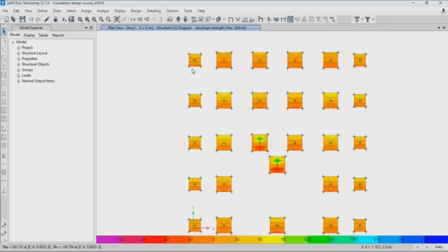Okay, so what it does is it designs the footing based on the pure physics of a flexing shear element. It is going to evaluate the exact stress at every single localized point in your mesh grid. Okay, so for this, you don't have to draw any strip. SAFE is going to look directly at your 0.5 meter mesh grid lines.